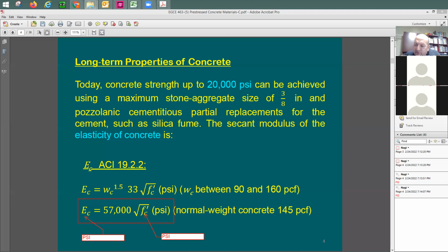So I went there, and even for the 2,500 psi, I buy it as 2,500 psi and they give me like 4,200 psi. So I said, okay, what can I do? I'm just going to order 2,500 and hope it's going to be about 4,000 when we come to testing. So it is not that easy to get to the concrete strength you want. It's just going to be stronger, but most likely not lower.